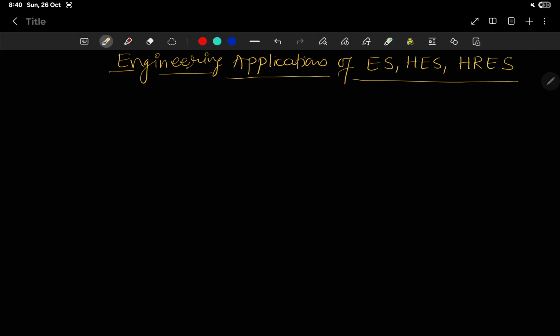So in previous lectures we have learned about different microstructure evolution at different regions, such as on the eutectoid point, hypoeutectoid point, and hypereutectoid point. We have seen that in eutectoid steel, below the eutectoid point, we get a lamella of cementite and alpha iron.